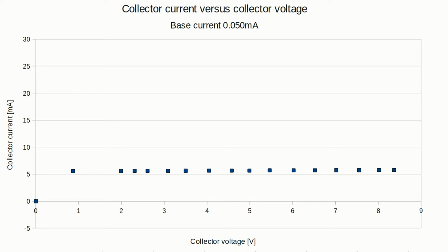Between 0 and approximately 1 volt, the current running through the collector pin is increasing significantly, but the measurement setup doesn't facilitate the observation of this area accurately. Besides some exceptional cases, transistors are not operating at these low voltages, hence we will not have a closer look at this area of the curve. Above 1 volt there is an almost linear correlation between voltage and current.